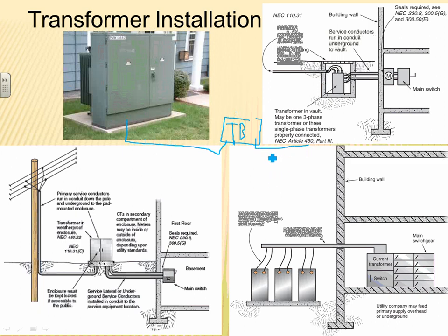So from this side, you might have 12 runs of 500 here. You could have probably seen that one. 500 kcmil coming into this termination box, so that's why they want you to size it kcmil. From their side, they might pull 8 runs or even less than that. 8 runs parallel of 500. So that's because of this, you get into the termination box.